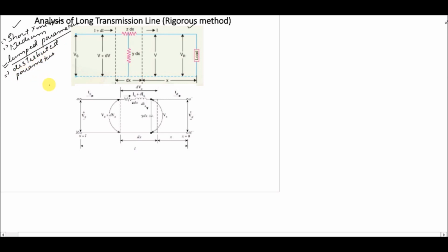These distributed parameters actually define the resistance, reactance and admittance value per unit length. So after every unit length, for example it can be meter or it can be kilometer, there is one resistance value which is in the impedance part of the transmission line, and there is a reactance value. So we have to model it in per unit. So we have distributed parameters in the long transmission lines if we have to use that, because otherwise there will be a very big difference between the actual results and the modeled results.